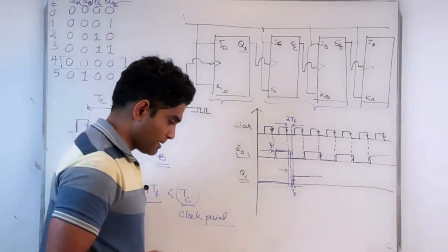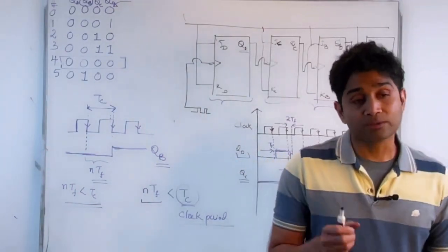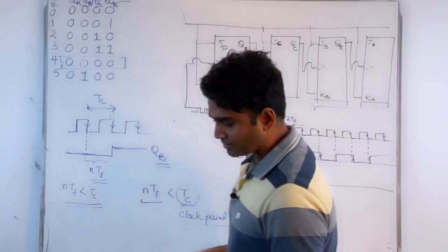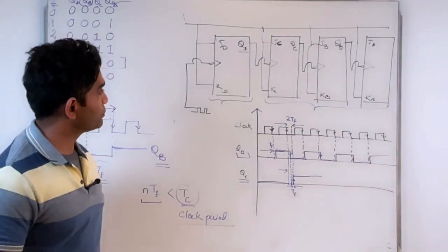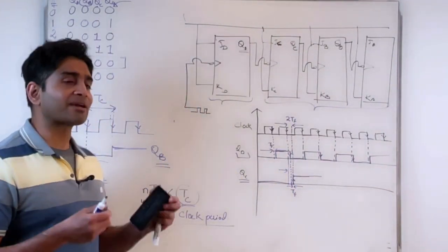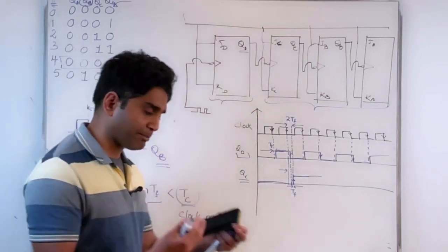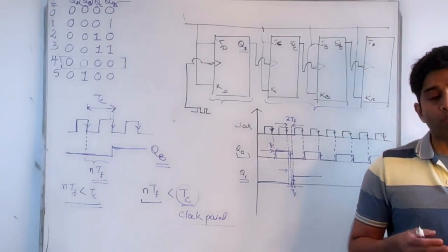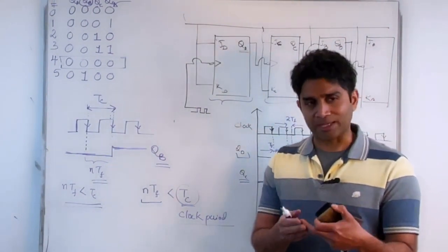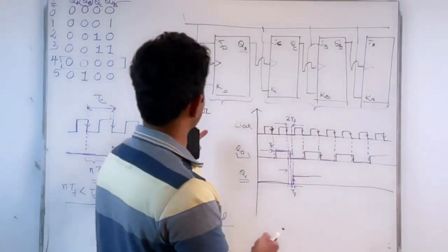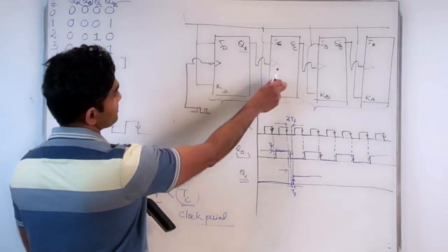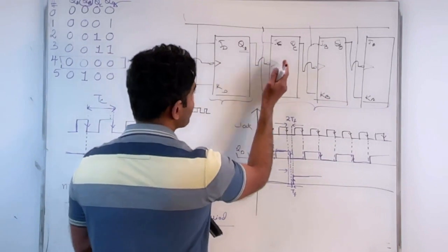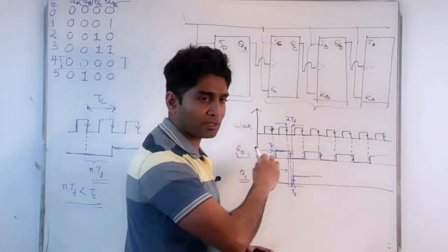All right. So this is a very important illustration of what happens when you don't synchronize each of your circuit elements with the master clock, or if you introduce components in the path of the clock. You don't want to do that. This is exactly what's happening here. We have introduced components in the path of the clock instead of synchronizing each stage with the master clock.